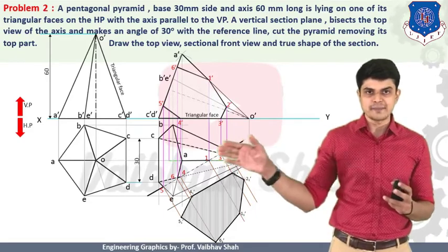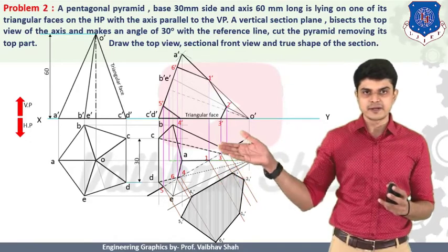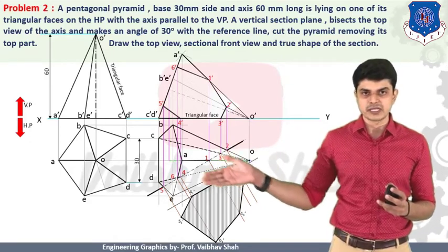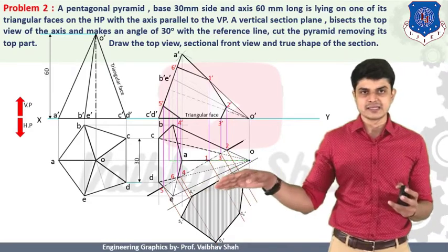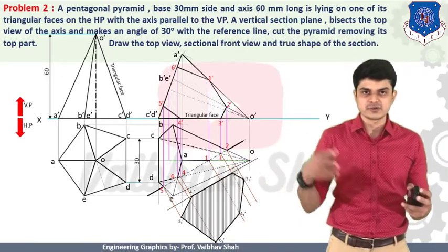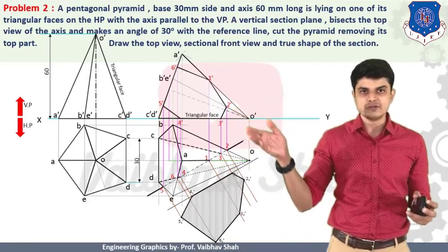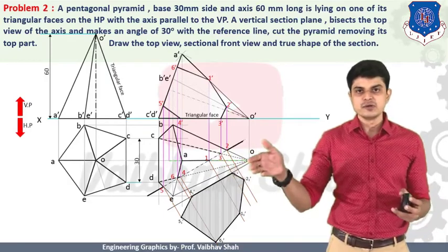You should draw a line parallel to this cutting plane line like this, and now you should draw the perpendicular lines from each and every point on your cutting plane line. Then after you should assume that this parallel line is nothing but your xy line in our case, and you should take the dimension of each and every point onto the xy line, and you will be putting that same dimension with respect to this new parallel line.